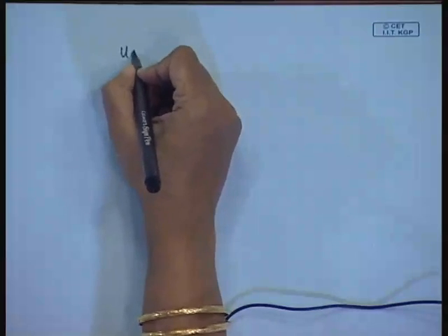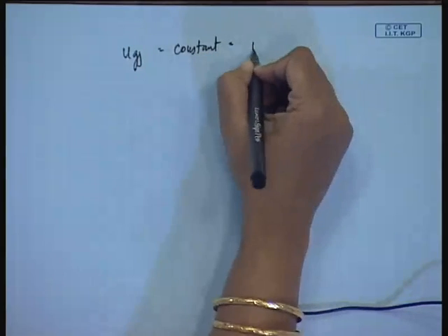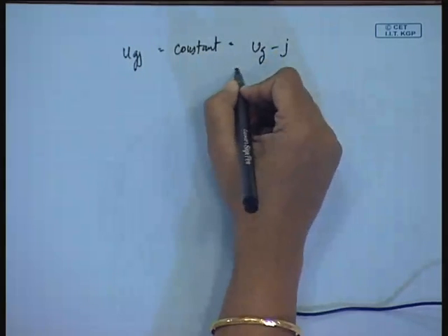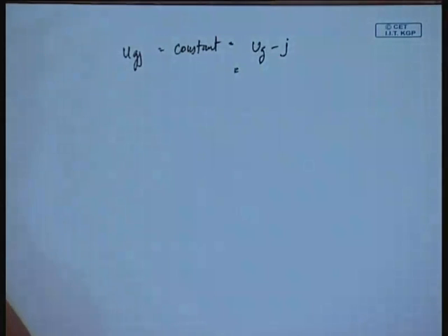Well, to continue with our discussions on the analysis of the slug flow pattern. So, till yesterday what we did? We found out that for the slug flow pattern, the relative velocity or the drift velocity UGJ was a constant, and this was nothing but equal to UG minus J, since all the gas is confined as slug flow. If I show you the idealized version which I had mentioned in the last class.